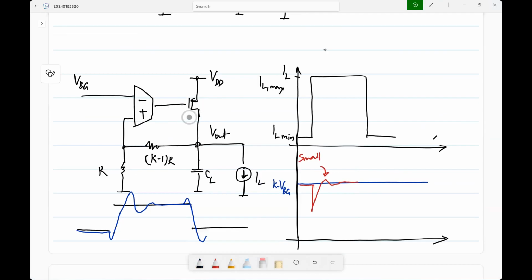At what operating point will you calculate the loop gain? Because you have to calculate small signal parameters and they are a function of the operating point. What will be the operating point for calculating this settling? No. Whether this rings or settles cleanly depends on the loop gain, which in turn depends on the GMs inside there and so on.